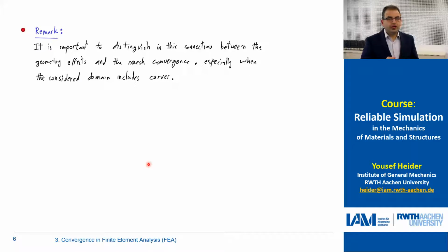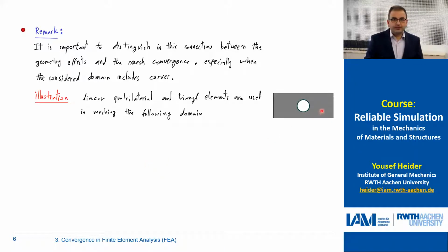Okay, so what I already talked about is related to mesh refinement in connection with stress concentration, but sometimes the geometry itself, how the geometry looks, may force us to choose fine elements. Take for instance this geometry here. We have a plate with a hole in it.